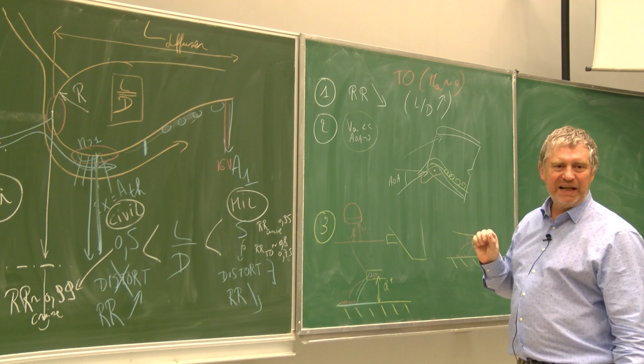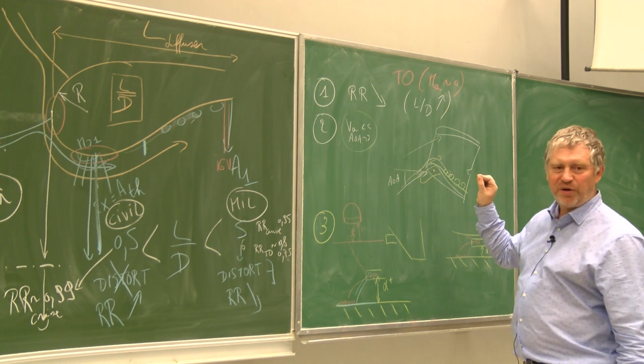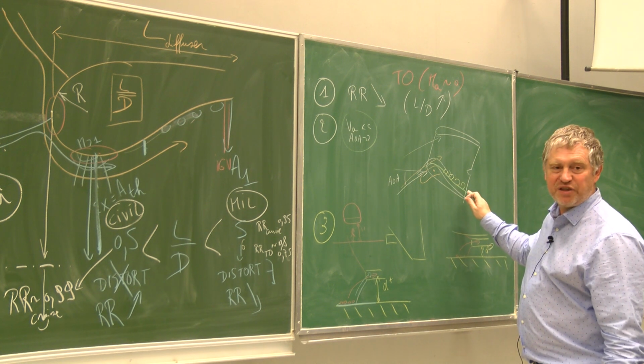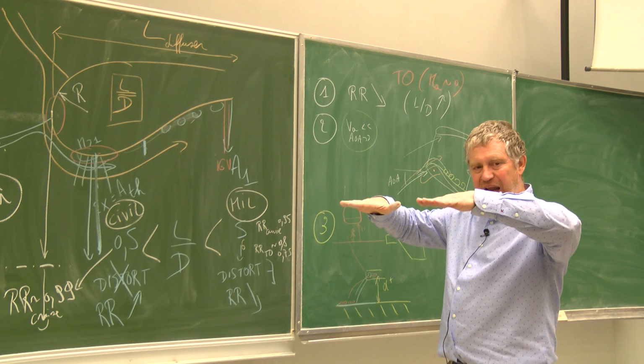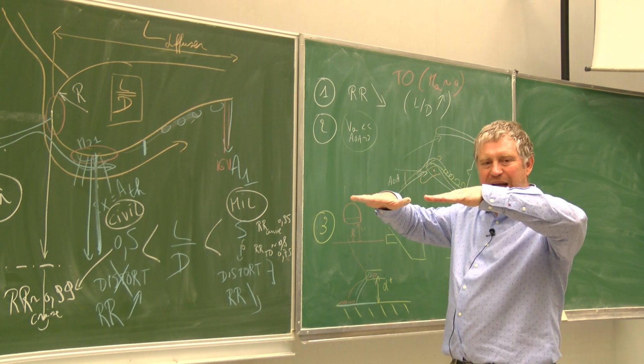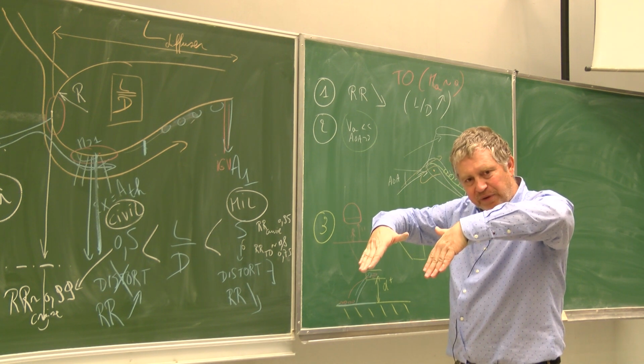If you can tilt the lower lip down, you see that the flow is entering without having this turbulence. So you have the lip that is like this, and when you are taking off or landing, at high angle of attack, you put the lip down.